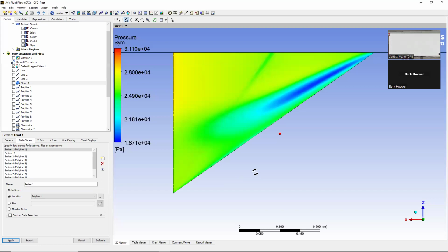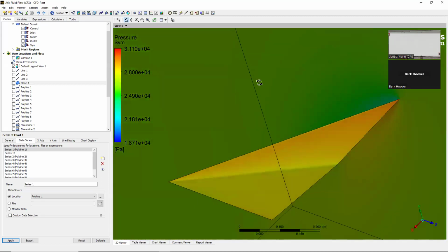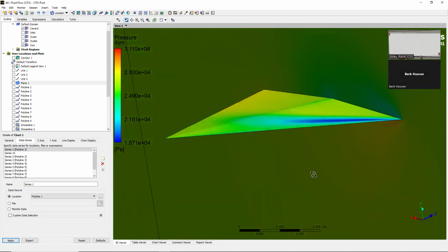Yeah, so here's Mach 0.5, I think at 15 degree angle of attack, looking at pressure on the wing. So that's low pressure, which means high speed. So you can imagine there is probably a vortex over there. It's the high pressure lower surface. There are all kinds of ways you can look at this.